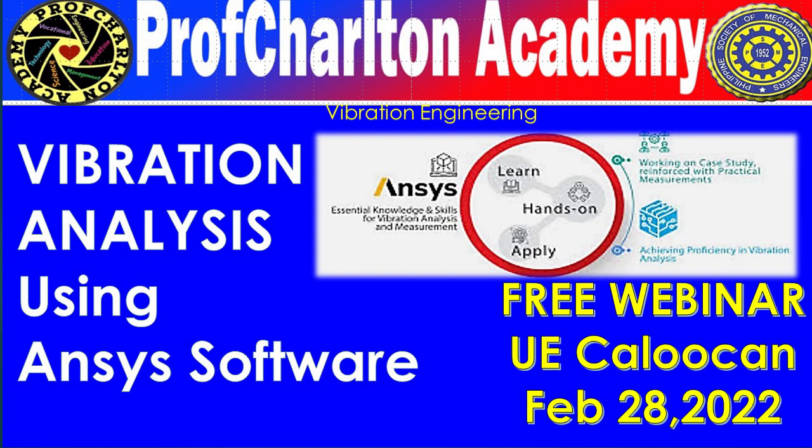If you go into stress, we have a lot of different stresses: von Mises stress, principal stresses, normal stresses, shear stresses. So let's insert von Mises stress. The stress generated on this component is 42.3 megapascal.